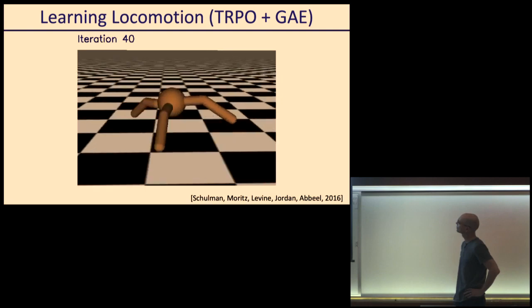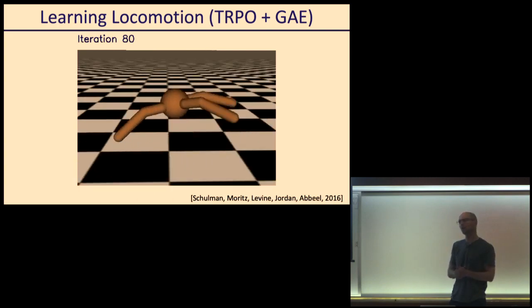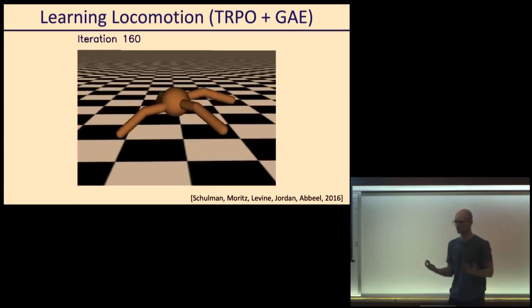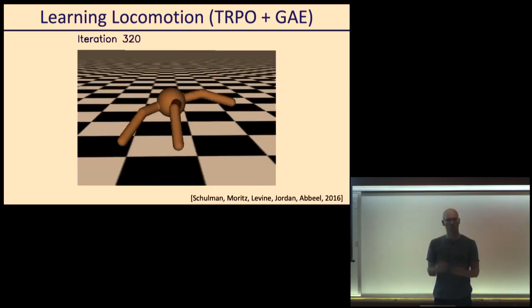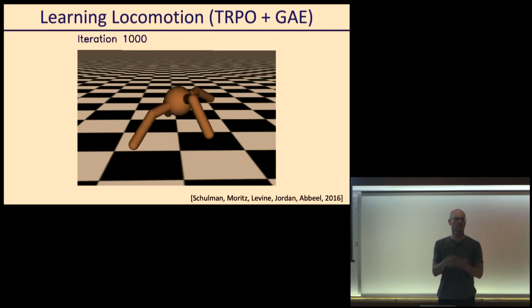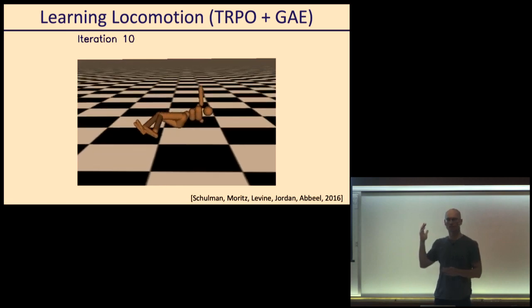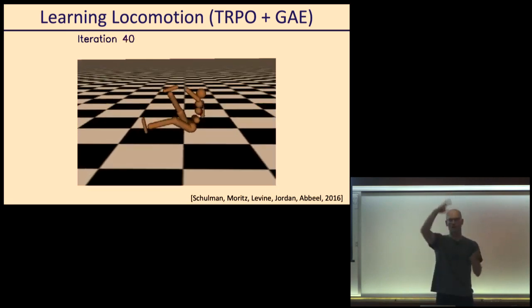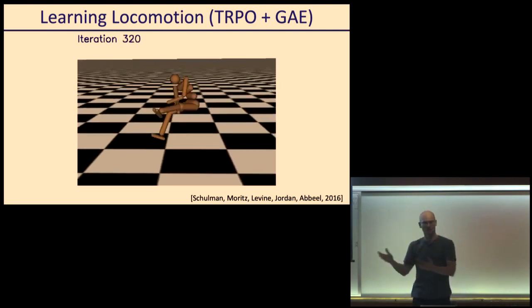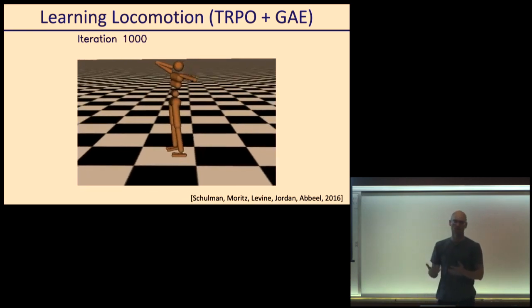There's a little bit of extra intuition there. If you look at traditional control methods, what's very popular is either you hand design something very crafty, but that's often hard to do. What else is popular is linear controllers. But linear controllers are limited in what they can do. So there might be time-varying linear controllers. But is time varying really what you want? It really depends on the state that you're in, which linear controller you should use, not on the time. And in some sense, that's what a neural network does. A neural network essentially has a bunch of layers that process the state you're currently in, and then at the very last layer, it outputs a linear controller. And so effectively what you're doing with a neural network is you're selecting the right linear controller for the current situation.